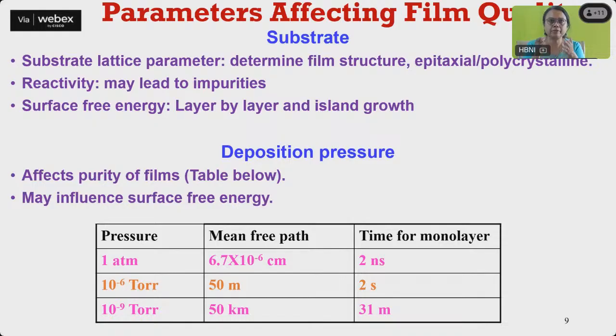Now, what are the parameters which affect the film quality? One is the substrate and the other is the deposition pressure. So the substrate lattice parameter is very important. Your substrate can itself be crystalline, like silicon, or it can be glass, which itself has no structure. So your substrate's crystallinity also determines the structure of your film.